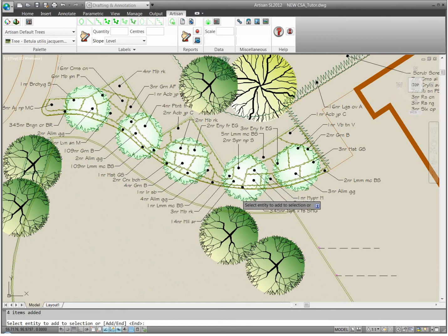Pick a point in the center of the last tree when prompted to specify leader arrowhead location, and pick a point to insert the label at the prompt to specify landing location. The new label is inserted into the drawing using the selected label template and preferences with a linking line connecting successive symbols. Move the label to the desired position if required.